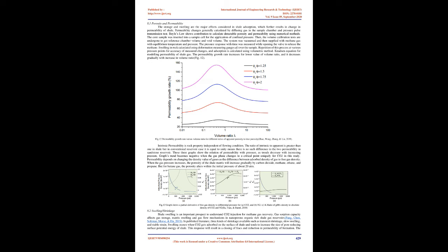This graph indicates the dependency of the experiment on displacing methane by injection of carbon dioxide. The breakthrough curve shows displacement of CH4 in the adsorbent cell from 100% mole fraction to 4% mole fraction with injection of CO2. Two simultaneous experiments showing the exact same path of gas displacement determine the reliability of the data outcome. Methane production with respect to time for a cumulative mixture of nitrogen and carbon dioxide gases injected in different ratios at constant pressure. Lee and Ellsworth, 2019.